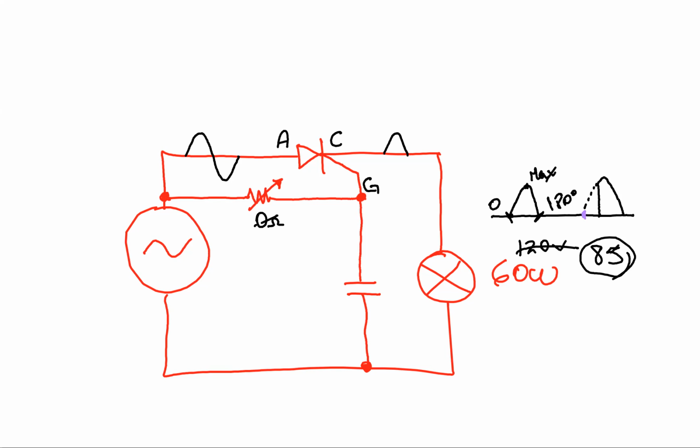So I was able to use a very small pot compared to a rheostat that I had to use before. And I was able to use a very small pot to control a large current, a large load, and at the same time, control the voltage on that load. And later on, when you go to level 3 and you see how DC drive and AC drive work, it's going to be beautiful to be able to control large horsepower motors with just a tiny small pot. And all this beauty happens because of the SCR.